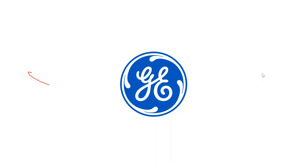So the way I would address that is, it is always versus the motor nameplate, right? If the motor nameplate says 4160, then yeah, you'd set that undervoltage at 90% and the overvoltage at 110%.